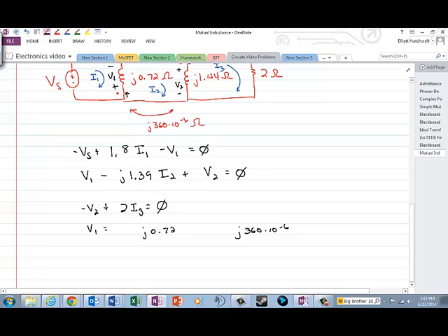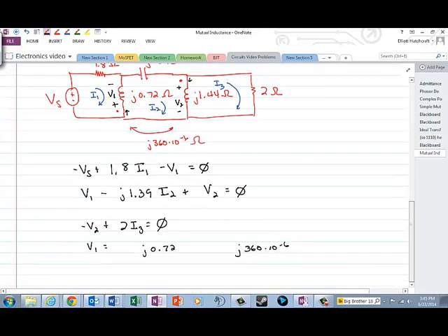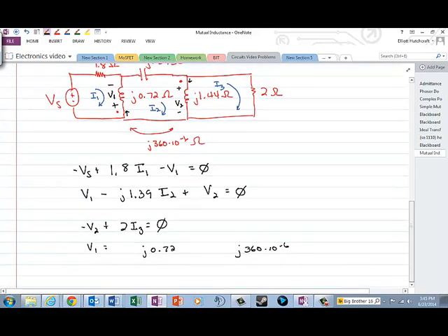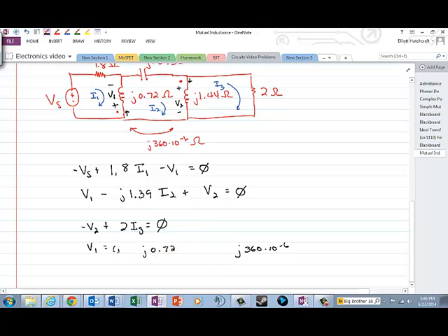Now the current that we're looking for, the current to satisfy the passive sign convention, is the current going into the dot there, and that's why we labeled that voltage V1 from the bottom to the top. For the current going into the dot, I2 goes into the dot and I1 goes against it, so this should be I2 minus I1.